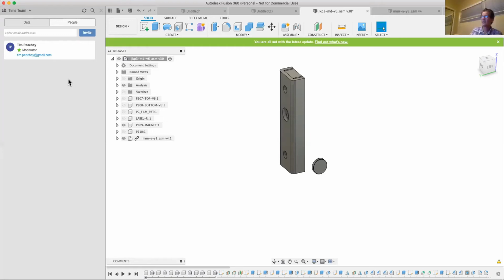That's a really key question, because you need to understand whether parameters are global or local. Within Fusion 360, I have not seen a way to make parameters global. They're restricted within the project that you're defining them in. So you can use length, width, depth in each different project.